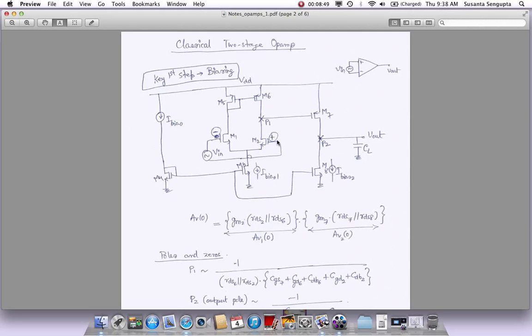This is the first gain stage, and if you take that output and go through a simple inverting amplifier, this is a PMOS type inverting amplifier, and its load is actually a current source load. So here also we're going to get gain from gate to drain, and we'll see what the gain is and we'll calculate all that out. And these two act as the current sources from this current mirror for these two stages. So you have two cascaded gain stages to provide high gain.